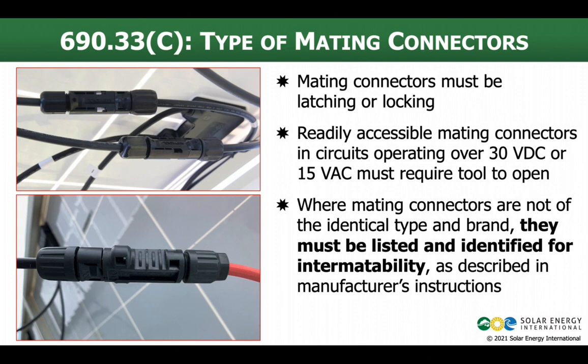Sometimes people want to say, hey, don't cut module leads off, even if you want to do it because you want to replace it with one that you can plug into the one that came connected to your DC to DC converter or microinverter. You've got to work your way through that because this is a code requirement now. It's really always been a requirement because of the way these products were listed. You've got to follow their instructions. It didn't say I could plug it into that other one. But now this has a higher profile, and it's something that we need to be aware of and address as an industry.